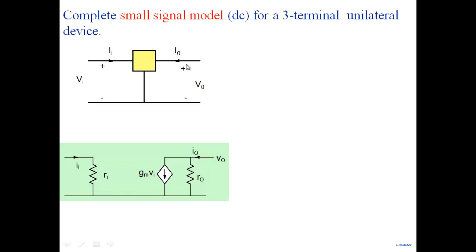And small signal models are nothing but whatever is the relationship between I0 and Vi and I0 and V0, whatever complex relationship it is, what we do is we linearize it. For small signal, the relationship we linearize around a bias point. It's like a Taylor series expansion. You have a Taylor series and around a particular point you do an expansion, right? So it's similar. You have an expression of current as a function of Vi and V0, whatever complicated expression. Around a particular bias point, you are making a little bit of perturbation, right? So you linearize it. And when you linearize it, you get linear terms.